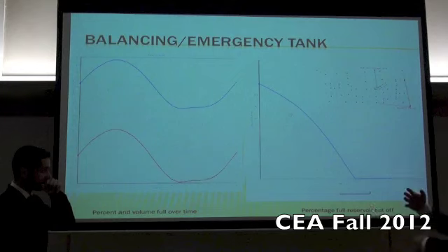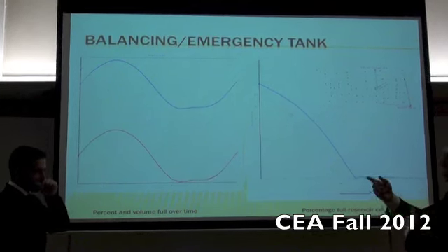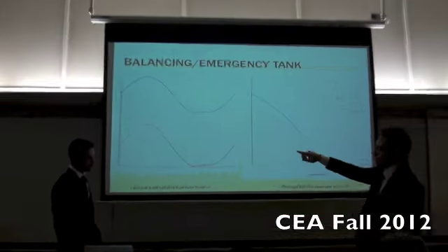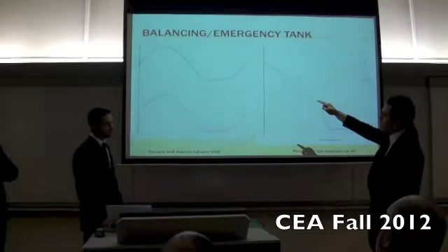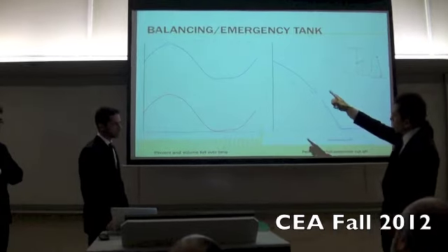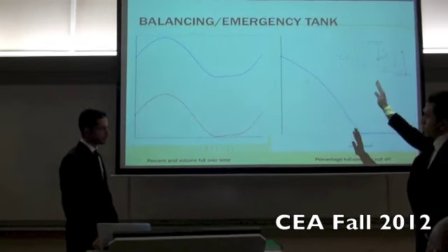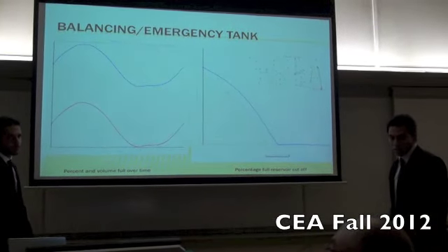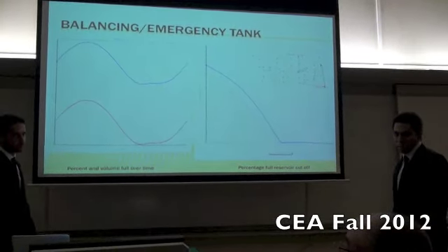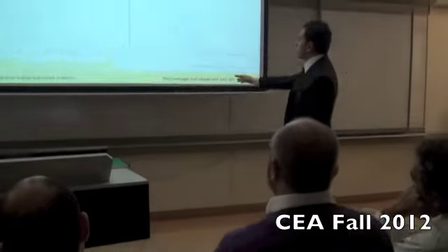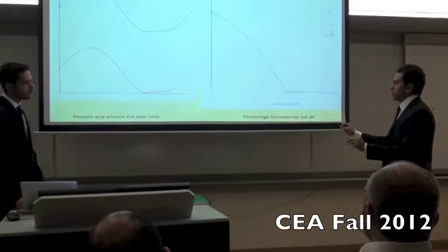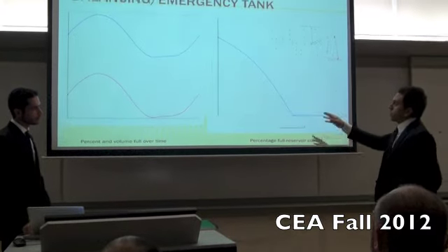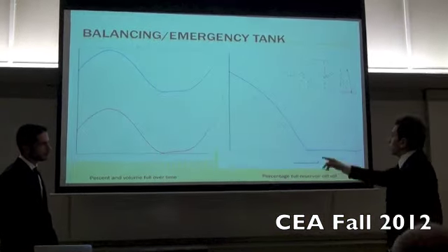This graph is inverted. It is the reflection of the pattern. When the demands are minimum, the tank is filling. When the demands are maximum, it's empty. Okay? And this is when the isolation valves are open in case of water supply cut off.